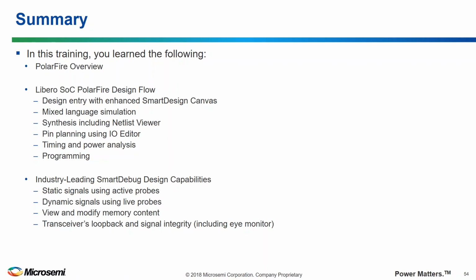The second question is, does LiveProbe use dedicated pins, or can these be assigned to any pin? They're dedicated pins, and you can specify when you create your project if you want to use the probes or not. So if you don't want to use the probes, then those would be available as user pins. Otherwise, there's two dedicated pins. When you look at the different pin assignments on the different packages that are available, you'll see a probe A and probe B. Okay, sounds good.